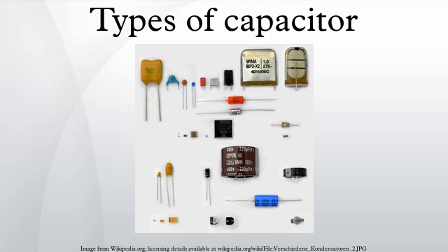Aging is fastest near the beginning, and the absolute capacitance value stabilizes over time. The rate of aging of Class II ceramic capacitors depends mainly on its materials. Generally, the higher the temperature dependence of the ceramic, the higher the aging percentage. The typical aging of X7R ceramic capacitors is about 2.5% per decade. The aging rate of Z5U ceramic capacitors is significantly higher and can be up to 7% per decade.